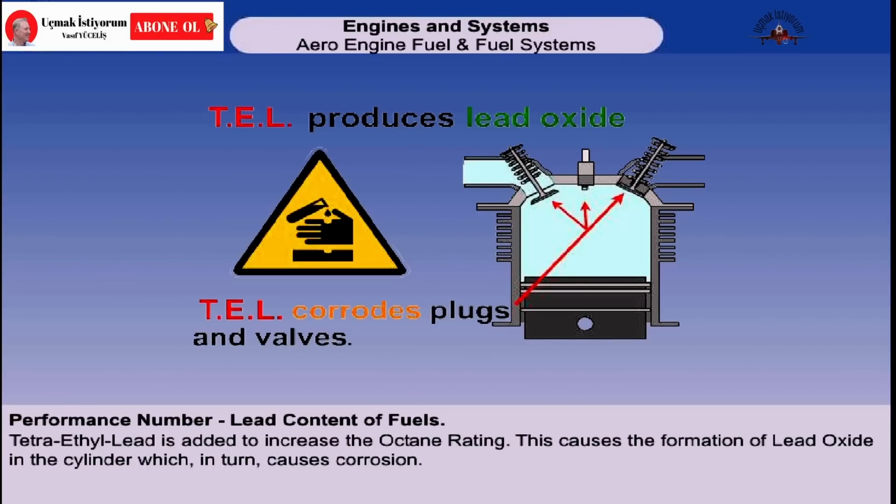To increase the octane rating of a fuel, tetraethyl lead, or TEL, used to be added. For instance, 2 grams of lead were added to each gallon of fuel to take its octane rating to 115/145. The action of tetraethyl lead is to reduce the formation of peroxides, which act as fulminates to explode the end gas. But it has to be used with care, as during combustion, lead oxide is formed.